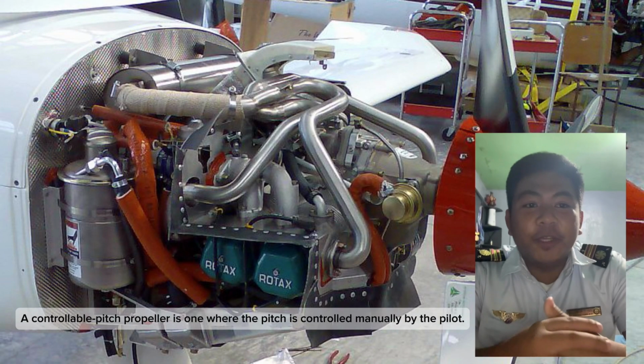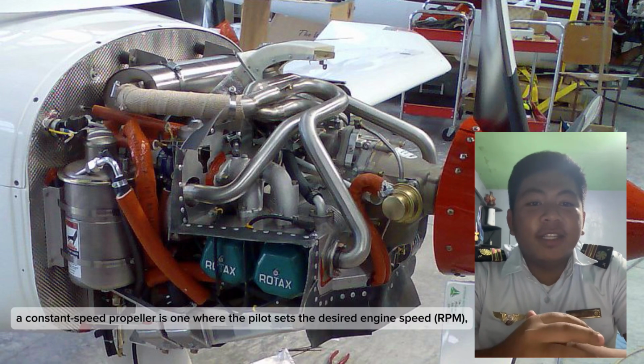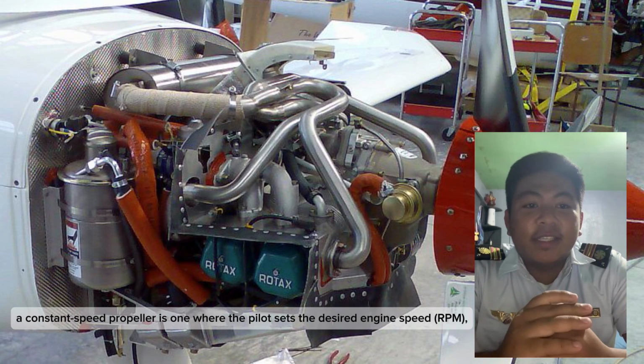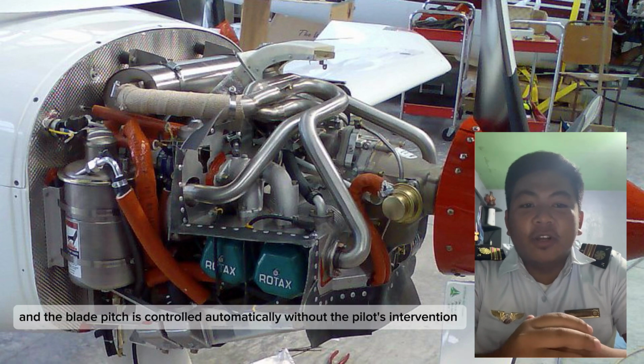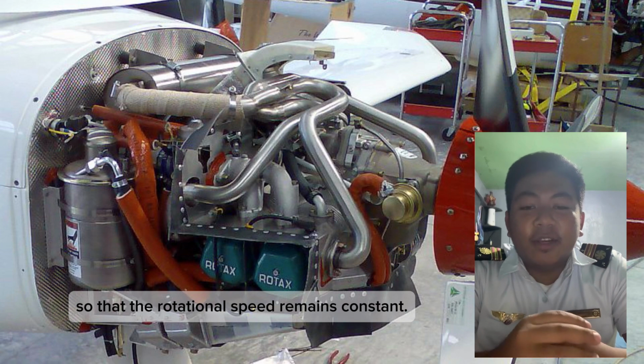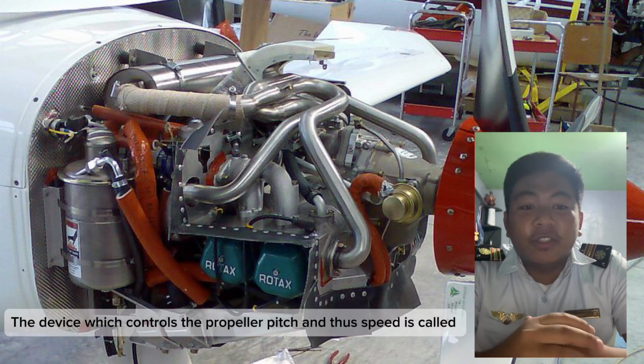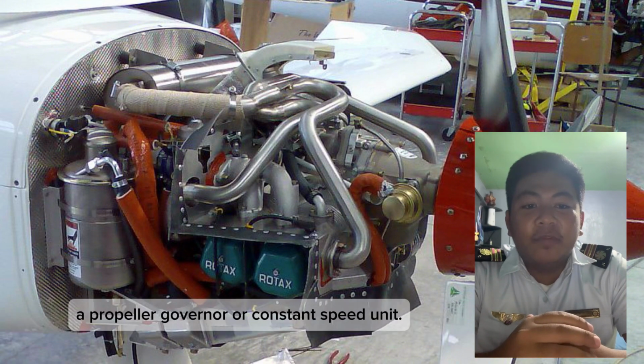A controllable pitch propeller is one where the pitch is controlled manually by the pilot. Alternatively, a constant speed propeller is one where the pilot sets the desired engine speed, or the RPM, and the blade pitch is controlled automatically without the pilot's intervention so that the rotational speed remains constant. The device which controls the propeller pitch and thus speed is called the propeller governor or constant speed unit.